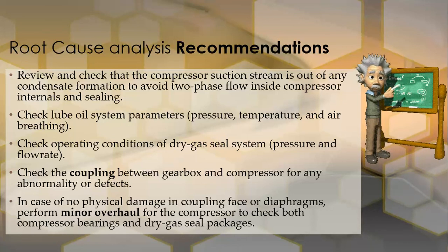We recommended also to check the coupling between the gearbox and the compressor for any abnormalities or defects, and today we are opening the coupling between the gearbox and compressor to check on the conditions, and I'm going to give you feedback on what we find. In case of no physical damage in coupling, face or diaphragms, we recommended to perform a minor overhaul for the compressor to check both compressor bearings and dry gas seal package, which will be an intrusive inspection.